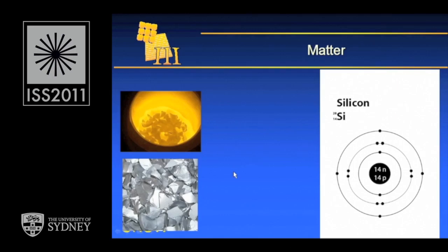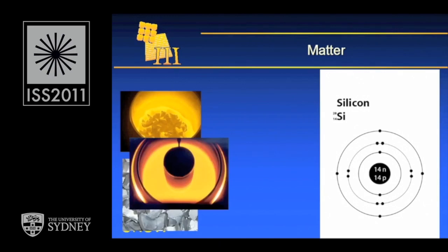To make silicon in a form that's useful for solar cells, you have to produce it so that the crystal structure of the silicon is well defined. If you just take silicon and melt it in a pot, it melts at 1400 degrees centigrade, so you have to heat it quite hot. Then into this molten silicon, you dip a little preformed crystal, a seed crystal, and slowly cool the silicon, which attaches to the seed. You can produce a very pure crystal of silicon, such as shown here.